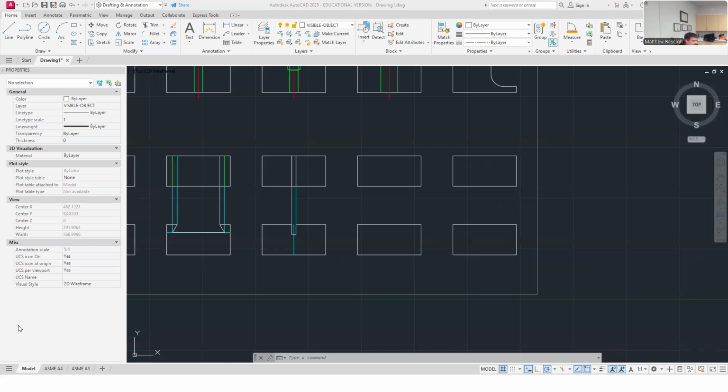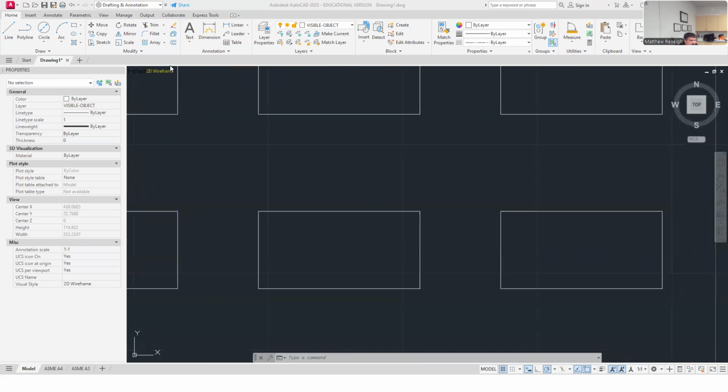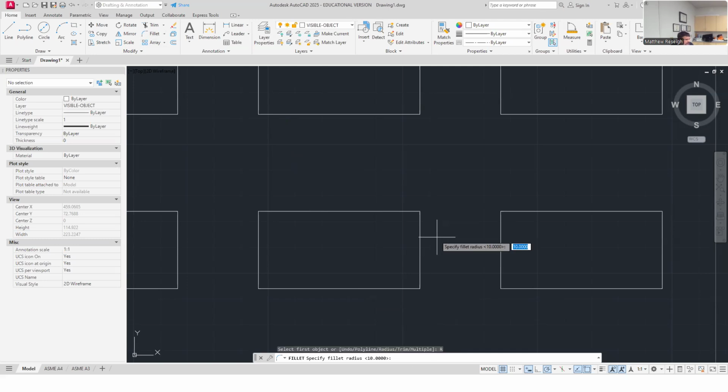And it says it's a radius of 30. This works well because I think I can truly use fillet and input the distance as 30. So if I choose fillet and the radius and say 30, enter. It just so happens I think that I can say from here to here, but it might not let me do that. Maybe I would use a circle. I'm not sure how you guys did yours. I was going to do a fillet and just let it cut it, but it will not do that exactly from two parallel lines. I think a circle would be a good one to use here.